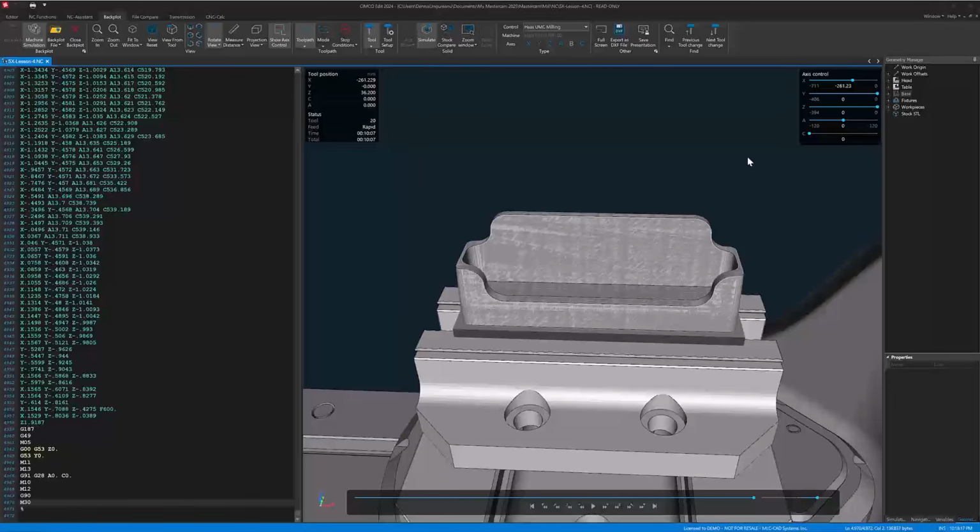But you'll be able to use this over and over and over on these machines, and it's great not just for 5-axis machines, but if you have a standard 3-axis vertical mill with a 4th-axis rotary on there, again, you have this big unit that's sitting on the table, and there could be potential issues for clearances. Depends on also the type of part and fixturing that you have.